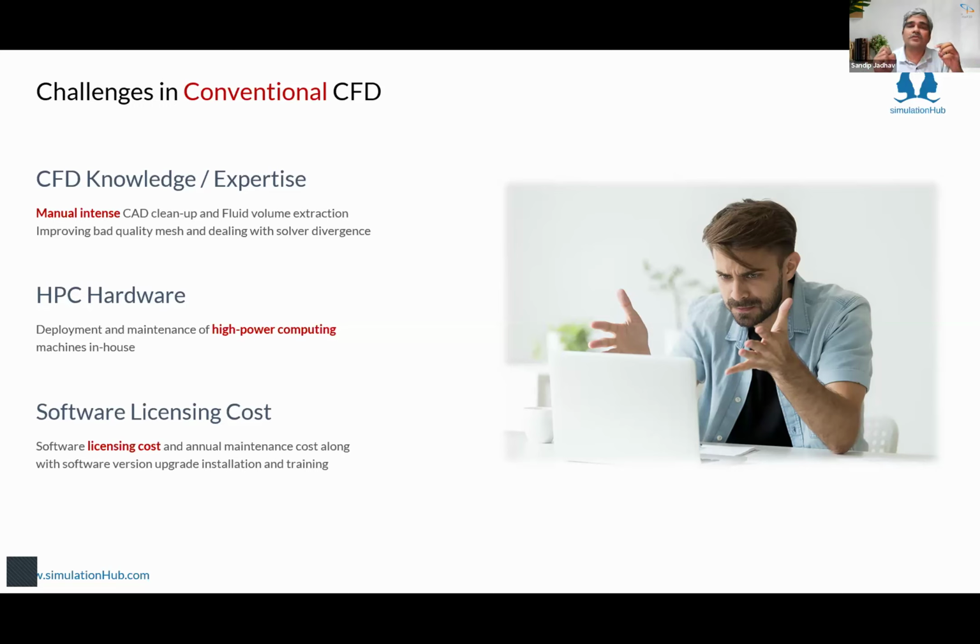It works with a single core. It works for a single user. Now, if you want to run this for a 24 simulation with a 30 million mesh count, you need HPC licensing. HPC licensing comes with 12 nodes. So if you want to run it, let's say nowadays on AWS you can get a 96-core computing machine, you need so many HPC licenses again. So the total amount of HPC licensing becomes really, really high.